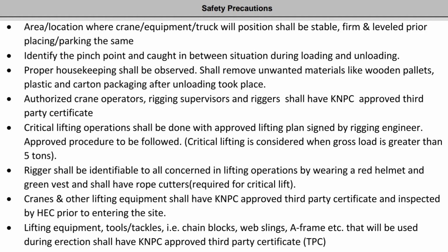Authorized crane operators, rigging supervisors and riggers shall have KNPC approved third-party certificate. Critical lifting operations shall be done with an approved lifting plan signed by the rigging engineer. Approved procedure to be followed. Critical lifting is considered when gross load is greater than 5 tons. Riggers shall be identifiable to all concerned in lifting operations by wearing a red helmet and green vest and shall have rope cutters required for critical lift.